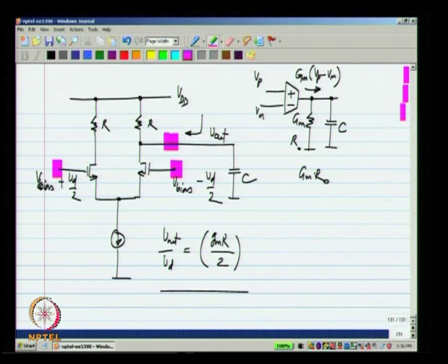Okay. To increase this gain value, we have to go on increasing the value of R, but if we increase the value of R, the DC voltage drop across it, I naught R by 2, will go on increasing. So, that means that we have to increase the supply voltage as well, to keep all the transistors in saturation region. Now, this is prohibitively expensive, it is just not allowed in real circuits, your supply will be limited to some extent. Okay. So, this is not a way of increasing the DC gain, we cannot make better op amps using that kind of technique. What we have to do is to substitute the resistance with something else that will look like a very high resistance, but will not demand as much a voltage drop. Okay.